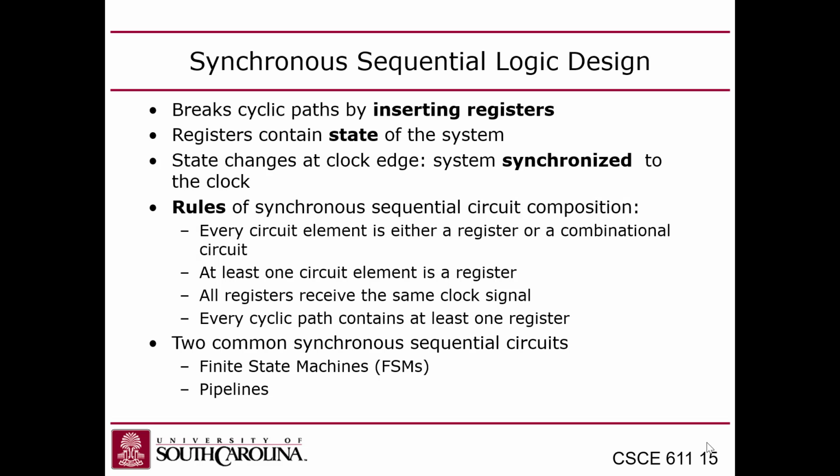That's kind of crazy because how many registers do you have on a chip? There's a lot. So that clock comes in and it gets fanned out to a whole lot of registers on the chip. So ASICs and FPGAs have specialized wires for the clock that are designed with a special structure, right?